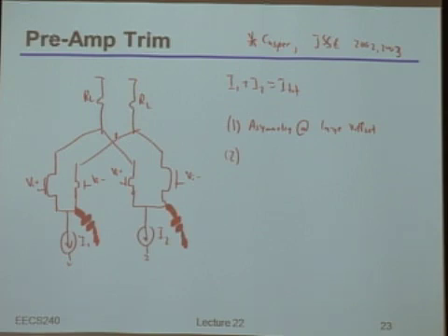And by the way, for those of you who haven't actually read it, asymmetry will matter because I've thrown noise on all your power supplies now. So you'll see it if things are actually pretty asymmetric. It'll actually show up as noise at your output. Any other questions on this?